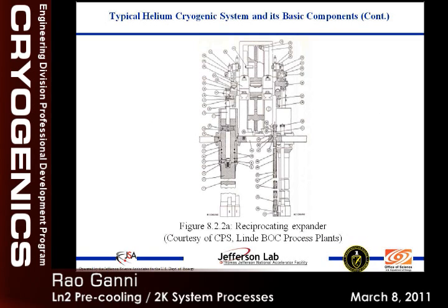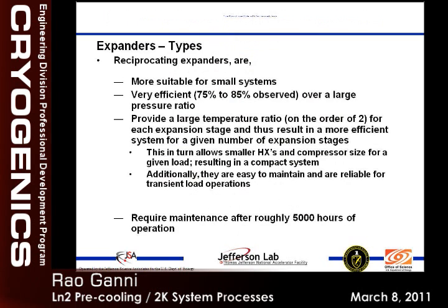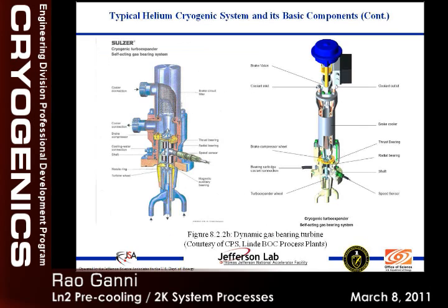So this is a reciprocating expander. We have quite a few at CTI, which does the 4K refrigeration, and the machine refrigerator, which is now presently owned by the POC. And this is probably more suitable for small machines. They have very good efficiency, and because we can change the speed, we can adjust the capacity by adjusting the speed. And these are the turbo expanders.